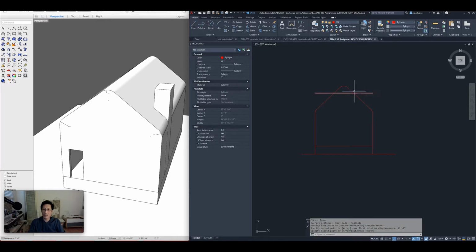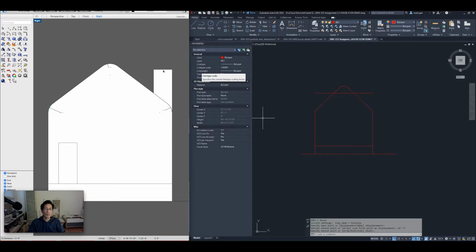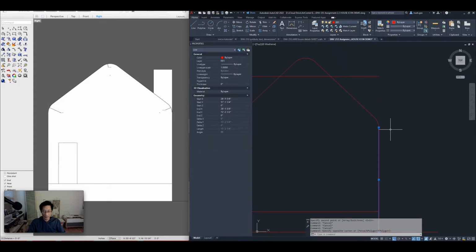So that represents the top of our chimney, which, oops, the right side, would be this line here, corresponds to that line. The right edge of it would just be the same as this line. And we know, we just measured in Rhino, it's 3 feet across this way. So what I'm going to do to draw the other two lines representing the chimney, for the outside one, I'm going to take this line already and rotate, copy it 180 degrees around this point.